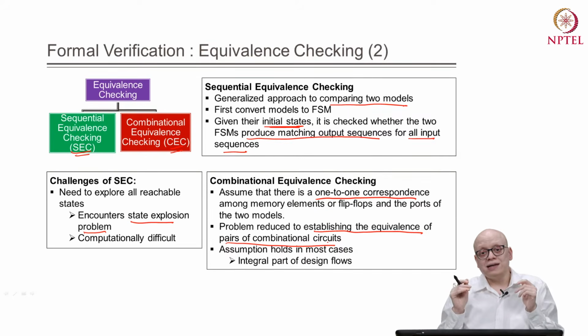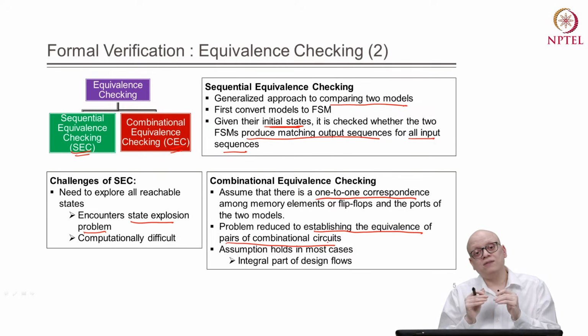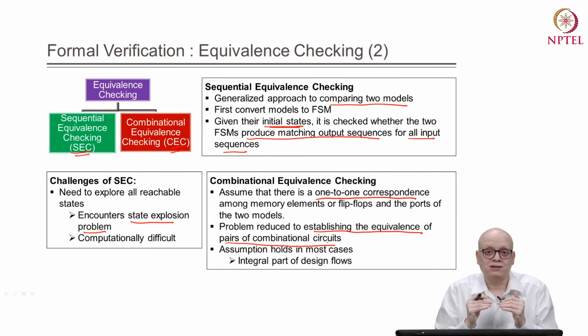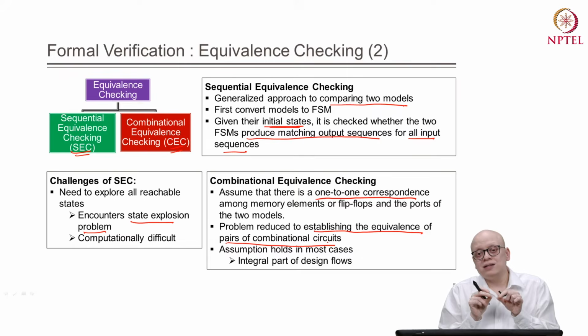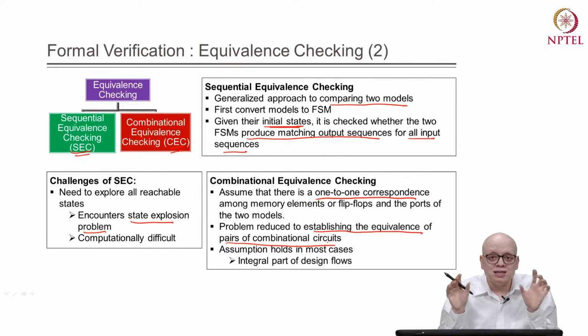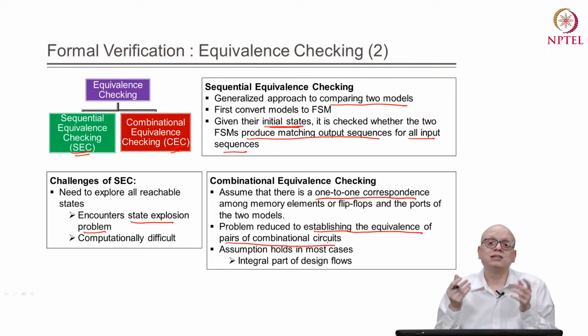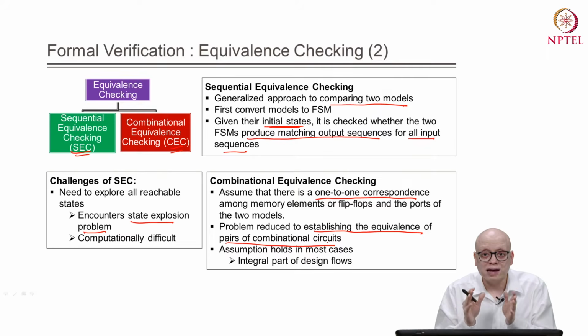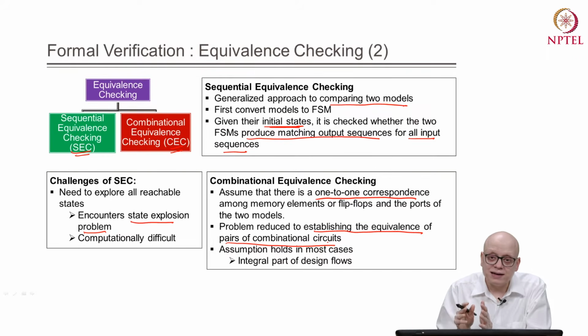The tasks in the VLSI design flow are typically incremental, and therefore the changes in sequential circuit elements like flip flops are not very disruptive. Small changes may happen because of, say, sequential optimization, and those can be taken care of by special techniques.